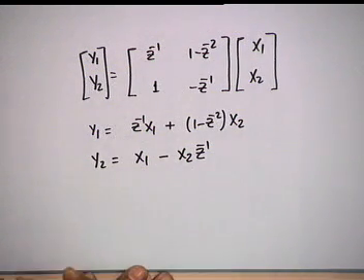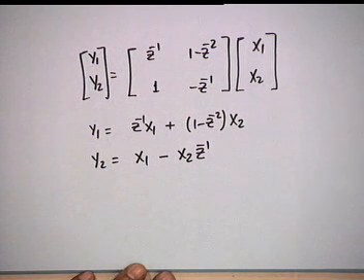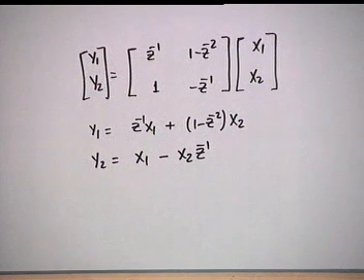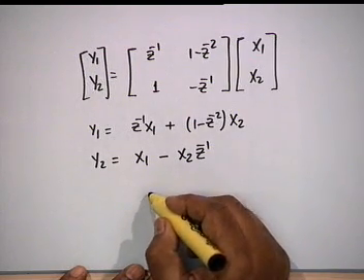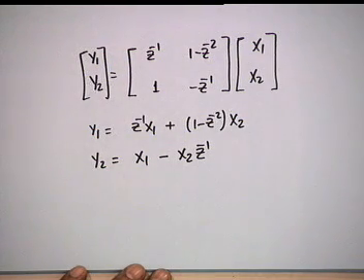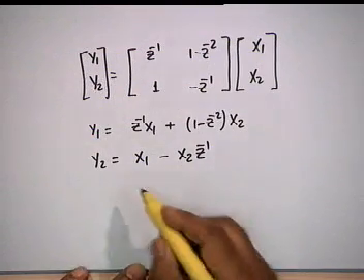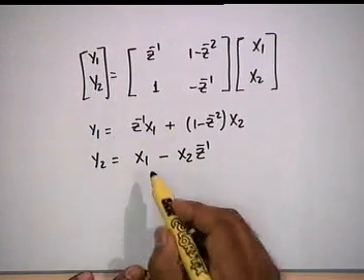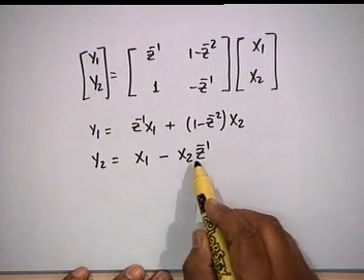Now, these have to be multiplierless, that is what we wanted. But you see, if I realize this directly, we shall require 2 delays, whereas we want only 1 delay. So, we have to do something to reduce it to 1 delay. You notice that if I multiply this y2 by z inverse, then I get z inverse x1 minus z to the minus 2 x2.